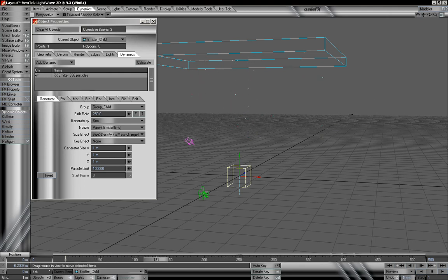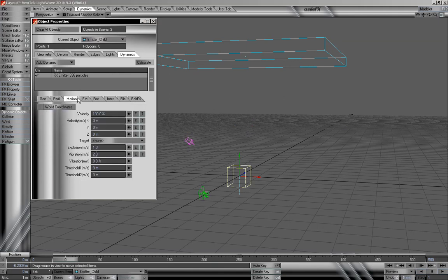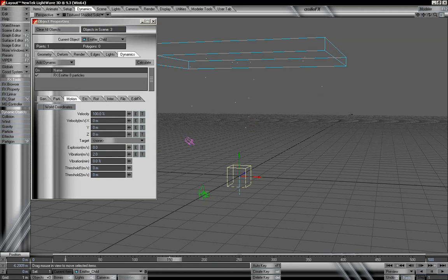So we can have each of these falling particles almost as if they hit the ground and then explode. And there's a way better way of doing that where we're going to set up a collision. But right now we're just taking a look at the way these particles are going to end and then explode. So one thing I'm going to do is remove our explosion. We'll set that down to 0. And now we can see them breaking up with the vibration.